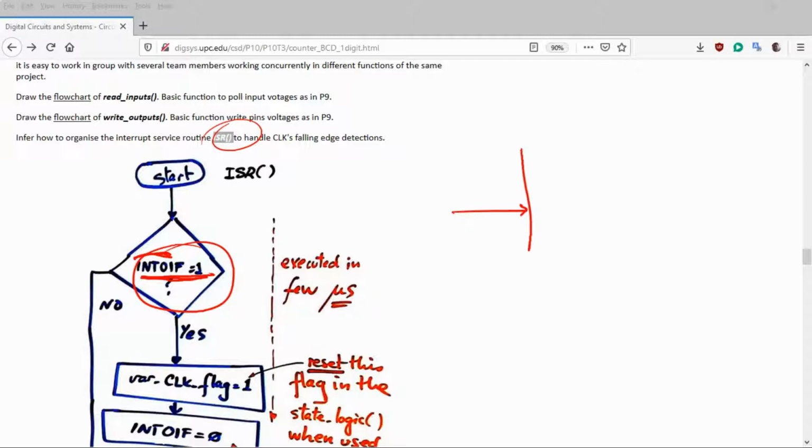You see, this is the INT0, this is the bit 0 in the port B, so this is what you like to detect, for example, a falling edge. This is the reason why I've got this jump to the interrupt service routine. That's a fundamental question, because if this is not the reason, something wrong had happened and the system has got out of control, because the system cannot reach the interrupt service routine unless it is interrupted by one of the sources that you have programmed.